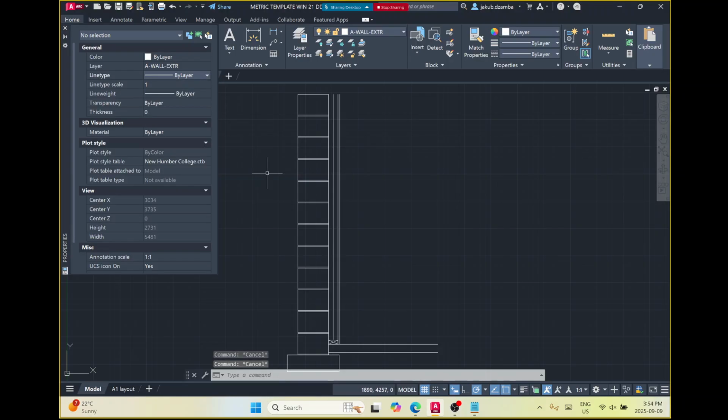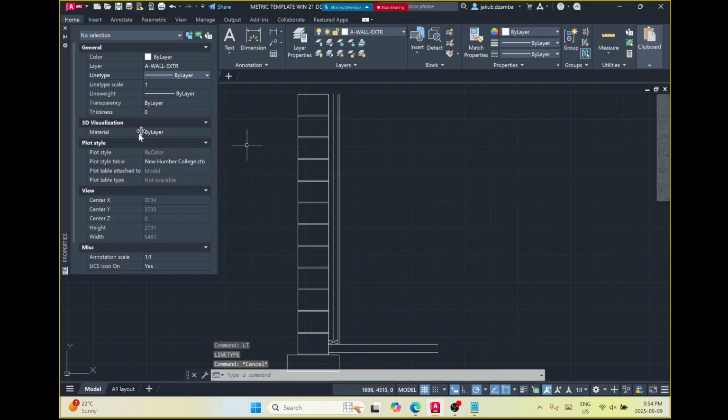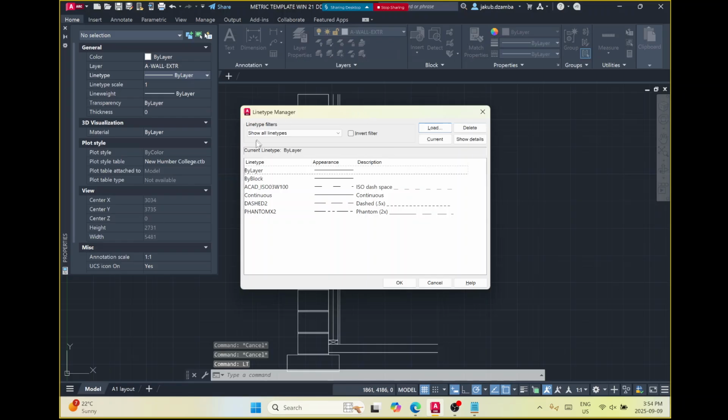So there is a, let me see here, LT. That's it. Okay. So we went one step ahead. So hit escape for a second. Type in LT, enter. LT stands for line type. Enter. And it gets you to that box anyway. So I'll figure out why you didn't have that menu you can click it from. But is everyone okay? Able to get to here?